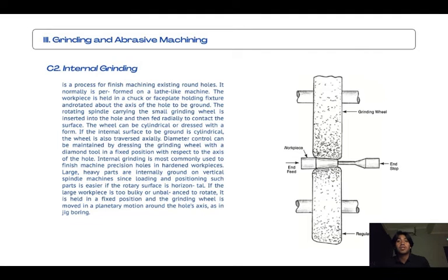This approach is used extensively in tool shops to make reconditioned dies and to produce machine surfaces on which there are moving parts with a reciprocating table. Horizontal spindle surface grinding can be used to machine slots in hardened workpieces by dressing a form into the grinding wheel, and a ground surface can be given a form rather than a flat surface.